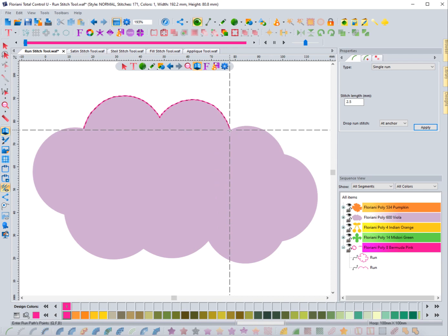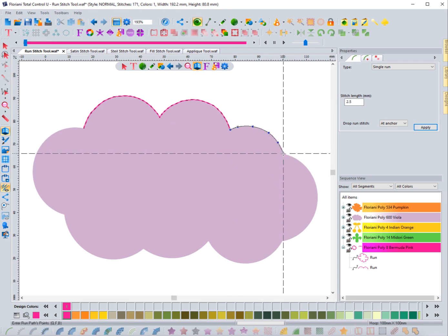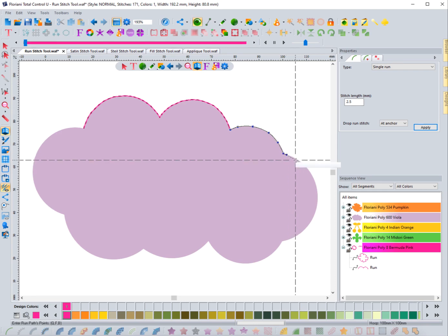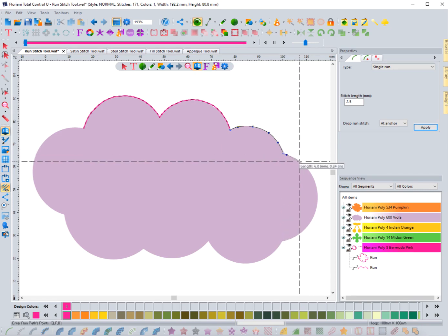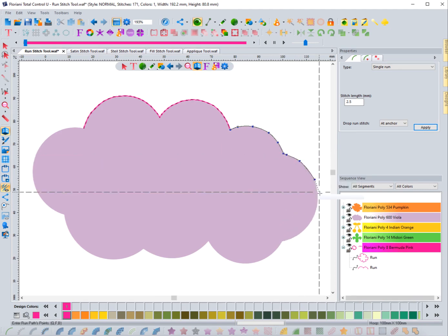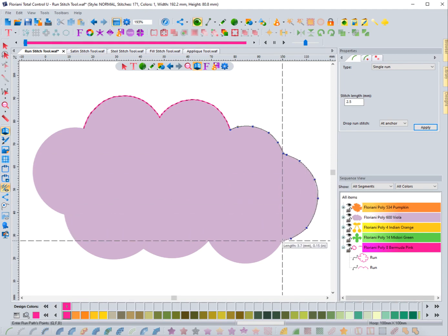I shouldn't have right clicked, but I'm holding down control, going around. I get to this point, I click that, still holding control. Now I'm going to go a little bit further, release the control key, drop a little stitch, so that it knows that I'm changing a direction, and now I can hold down control and keep going. So I'll keep going here, and I'll get to this point, and then now I'm going to release the control key, drop a little point here.